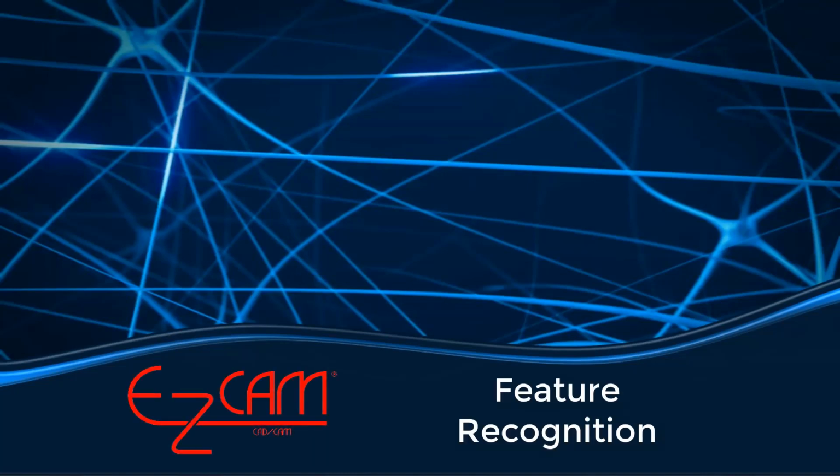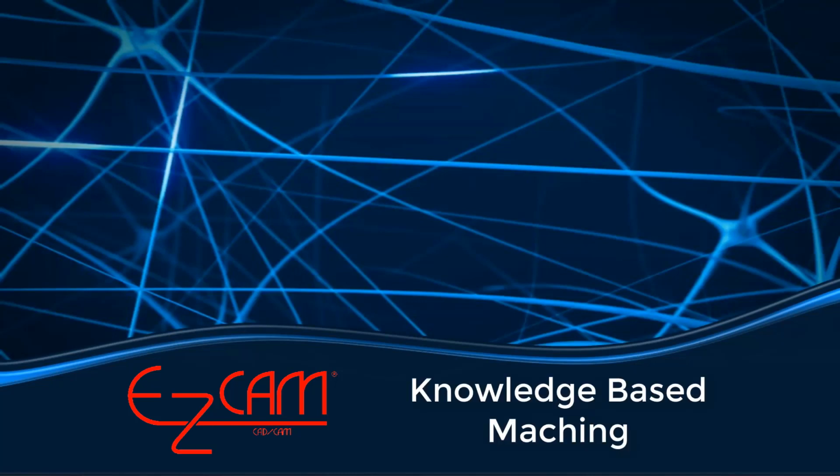CAD-CAM offers feature recognition. Pick a pocket and CAD-CAM assigns all your machining strategies. The same is true for all other part features. We could also call it knowledge-based machining. Just point and click and you get the coolant where you need it, depth of cut is taken care of, and any other information needing an explanation. All that information is stored in a part's feature.